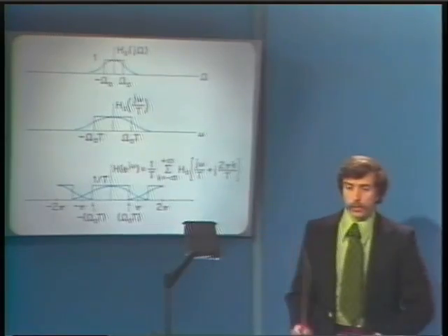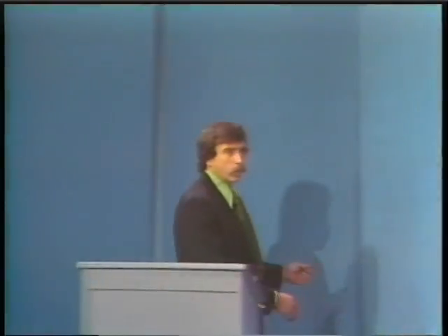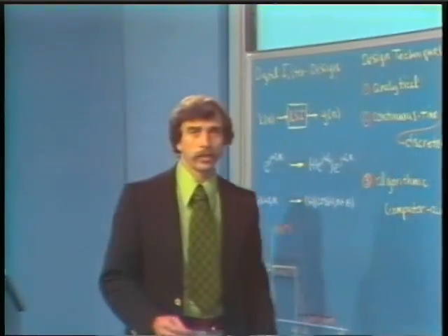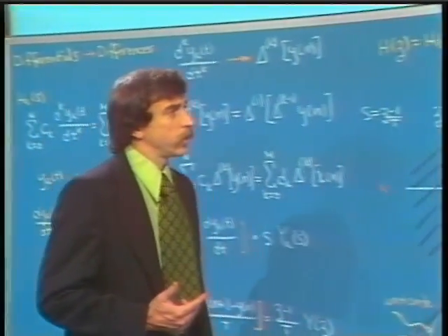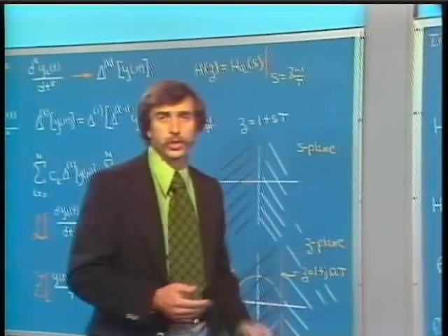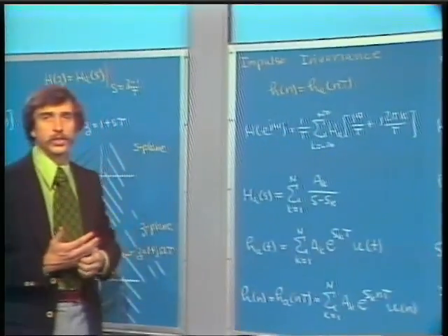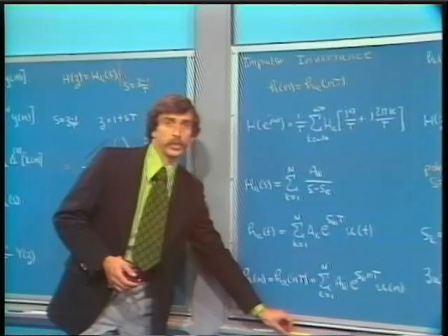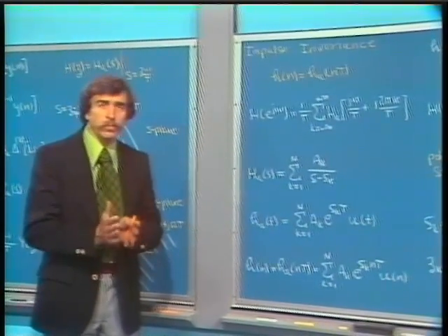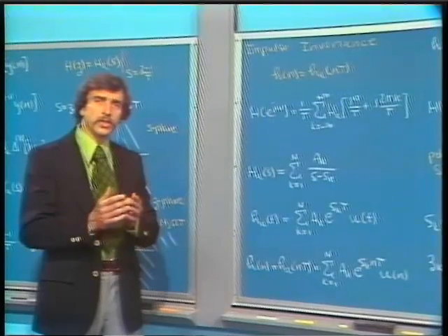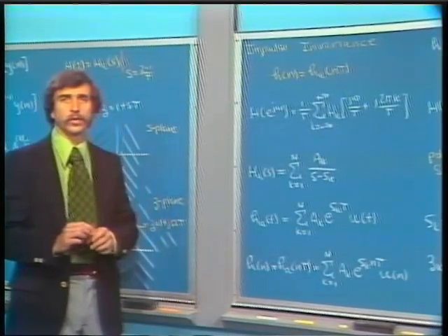All right, so with the impulse invariant method, one of the important advantages is the fact that it tends to preserve good time domain characteristics, that is, the impulse response characteristics were preserved, and also it provides a linear scaling from analog frequency to digital frequency.